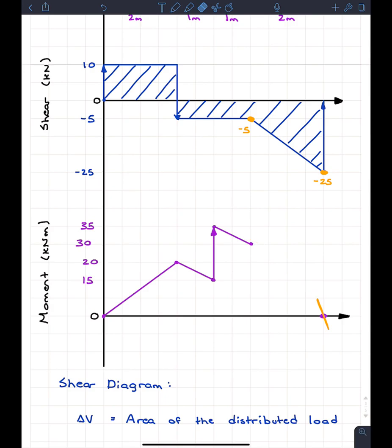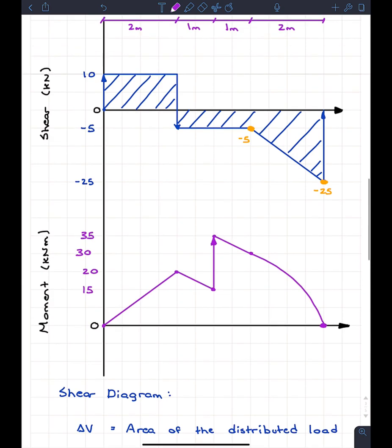So we come down here and we can put in, oops, go back to purple. We can put in our nice quadratic curve like this. So it must go like this, where the slope gets continuously steeper as the shear goes on. And that's how you figure that out. And I know it's really confusing, so I recommend just maybe looking at it and just look at the shear. We got to find out how the shear is transitioning, and that transition is the slope of this one. So we see it goes from -5, so a pretty nice gradual slope, to -25, which is going to be much steeper in that side.